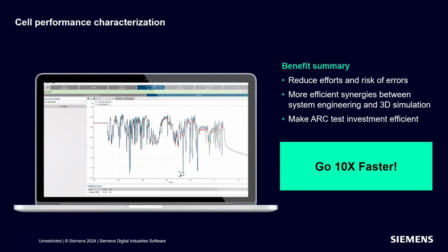Basically, with this virtual performance testing, you can go 10 times faster, reducing experimental time and breaking barriers between test and simulation. You can virtually determine parameters for both equivalent circuit models, RC, and thermal runaway models. And while ARC testing, accelerated rate calorimetry testing, will ultimately still be required to verify and calibrate thermal runaway models, you can make the investment in that expensive test easier by creating a physics-based thermal runaway model capable of predicting different scenarios.